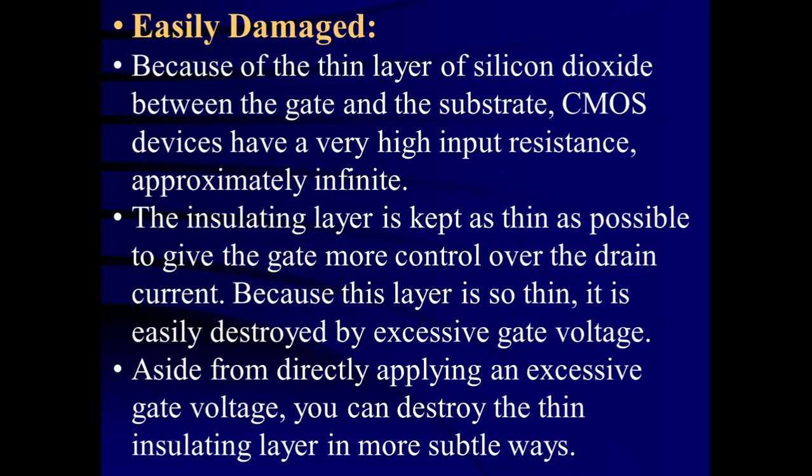substrate, and next to that p-type substrate an insulating layer of SiO2 is kept, which is a very thin layer, and then there is a conductor gate. So between the gate and substrate there is a thin layer of insulating SiO2, a non-conductor. Now, to have control of the gate voltage over the drain current, that is called the input-output characteristic. That is, the gate voltage has control over the drain current ID.